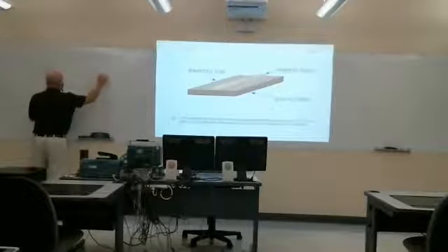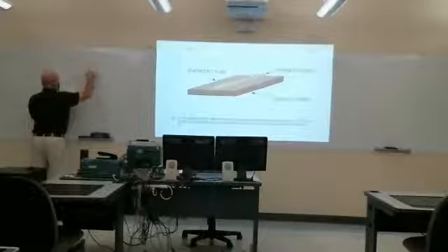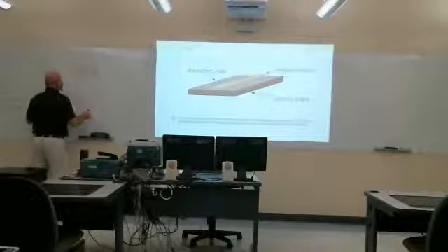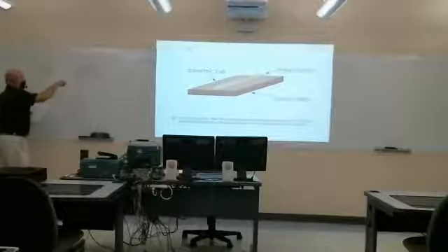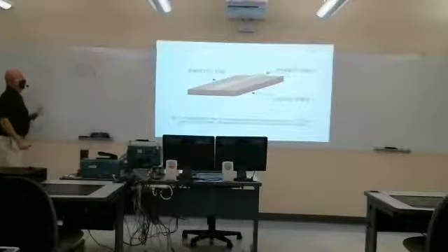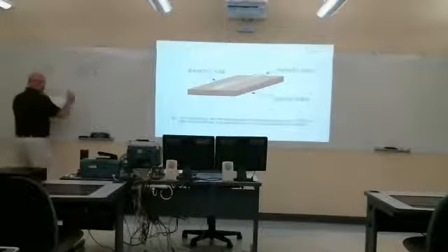And then in a microstrip, you've got the ground plane and then a conductor. The E field goes from the conductor, and the B field is transverse to that. E cross B is actually into the board. I'm showing the conductor running that way, and so the signal would be running into the board there as well. So this is microstrip.